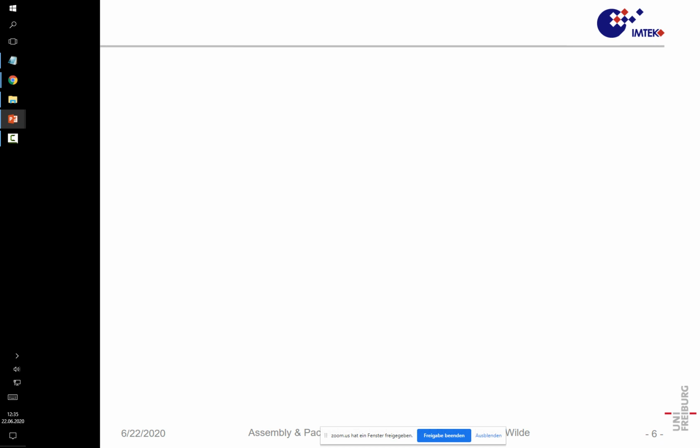Describe a CTE-affected failure mechanism for substrate material of printed wiring boards. What are the failure causes? Make a sketch and a quantitative evaluation of stress. That's also something very interesting in order to describe which problems we might have.